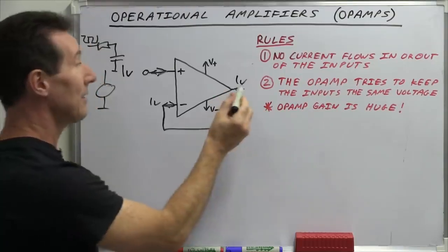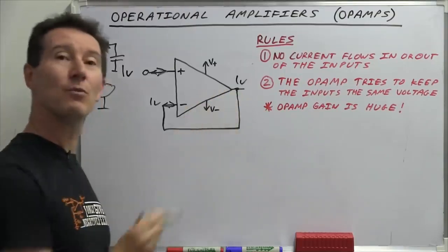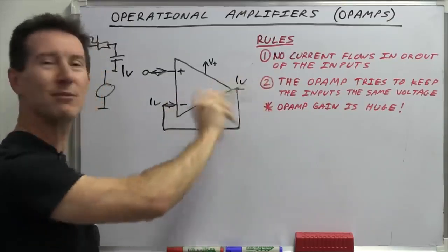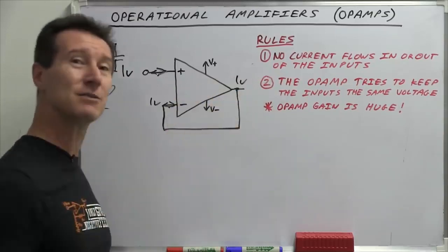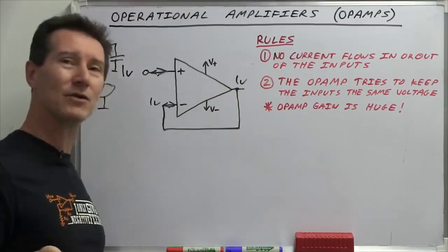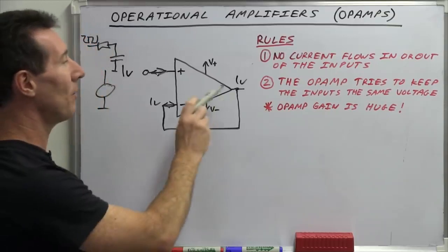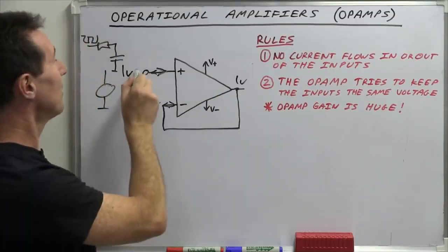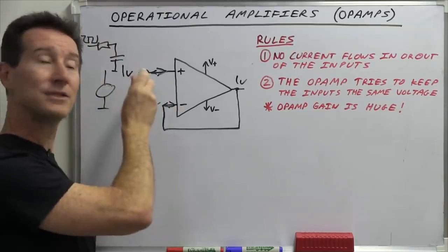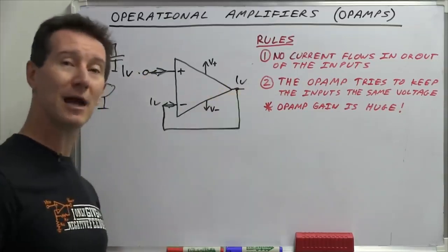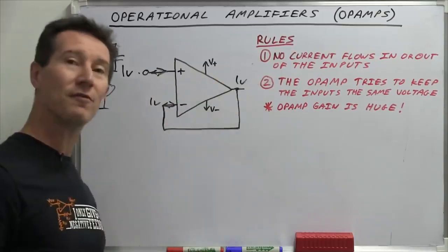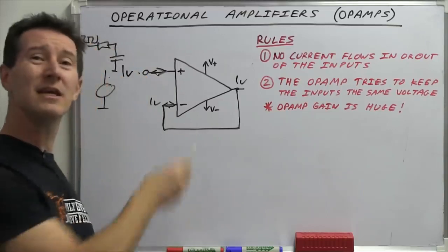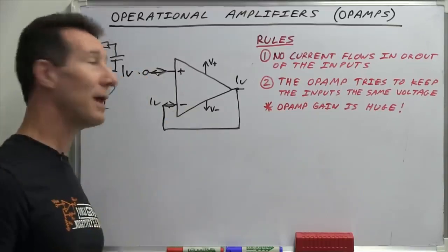It's what's called a very high impedance input, essentially open circuit, so it doesn't disturb anything you hook up to it. But the op-amp has what's called a low impedance output, so we can drive a reasonable amount of current, milliamps, tens of milliamps, that sort of thing. Some can go as high as a couple of 100 milliamps for your power op-amps. So that's why it's buffering the signal, a high impedance signal, and giving you a low impedance output. It just allows you to drive things with a sensitive input like that. Pretty easy, very useful configuration, the op-amp buffer.